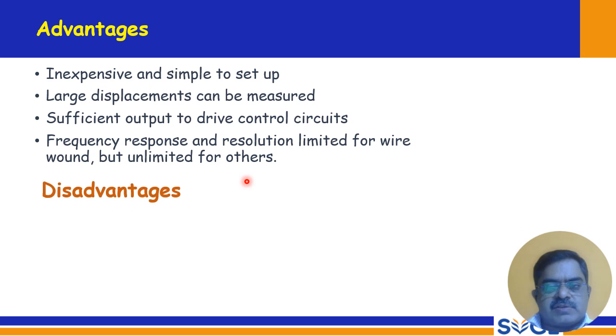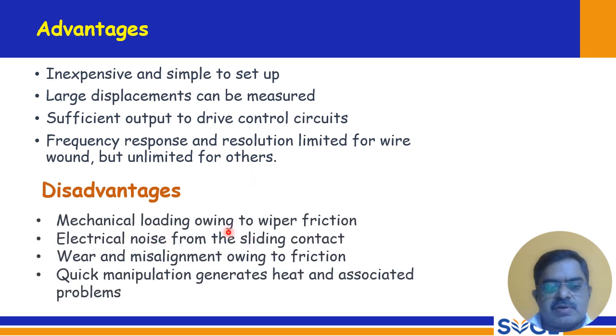So disadvantages are mechanical loading owing to wiper friction. So it is a contact type. Electrical noise from the sliding contact, wear and misalignment owing to friction. Quick manipulation generates heat and associated problems. Wherever you find heat, there will be more problems, or we can say the material can even burn out very quickly because of higher temperatures within the material.